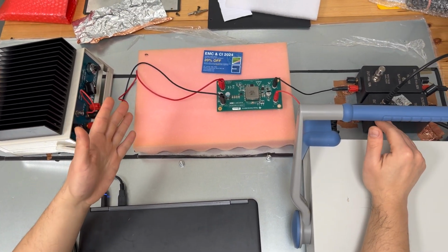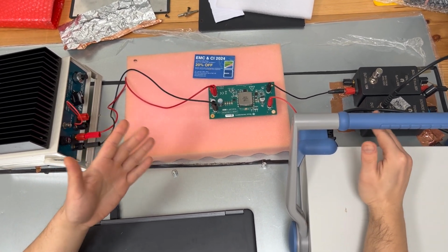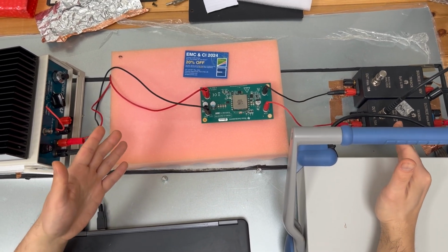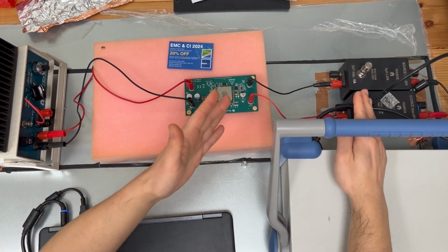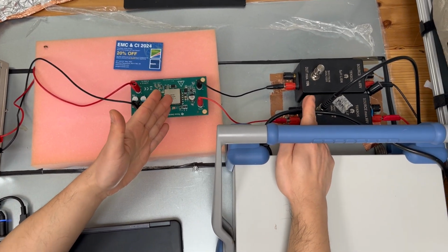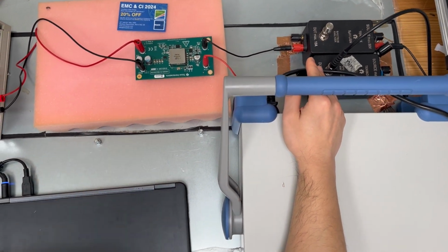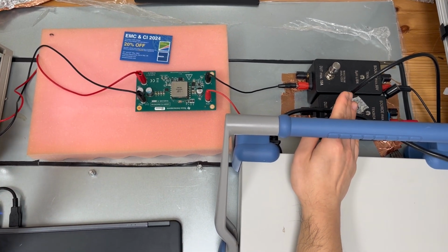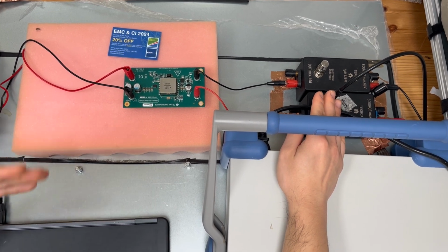Now, one of the things you may ask, and actually lots of people ask, is: Min, when we set up, for example, an automotive CISPR 25 conducted emission test, why does the standard say that the cable length has to be less than 20 or 30 centimeters long? Why do we need to have this insulation support? Or in other words, if we had longer cables, what kind of effects will it bring? So in this case, let's demonstrate.